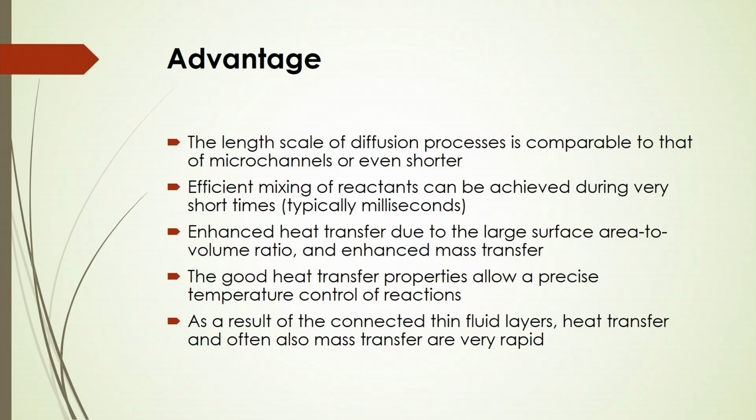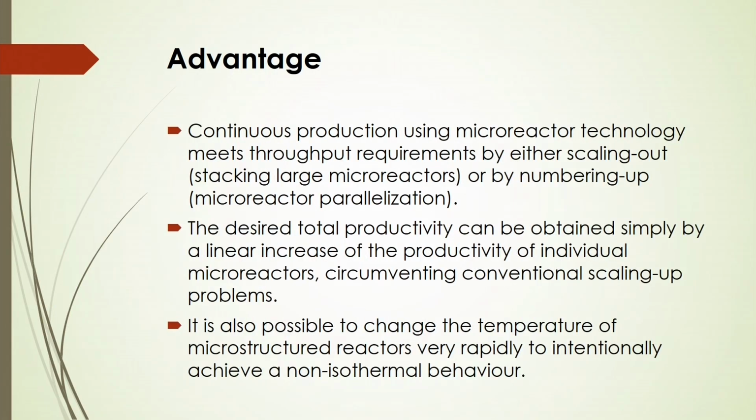You can get efficient mixing of the reactants, which can be achieved within very short times, typically milliseconds. Enhanced heat transfer due to the large surface area to volume ratio, and also enhanced mass transfer. Also you can get good heat transfer properties that allow precise temperature control of reactions. And you will see that heat transfer and mass transfer will be more rapid in this microchannel based reactor.